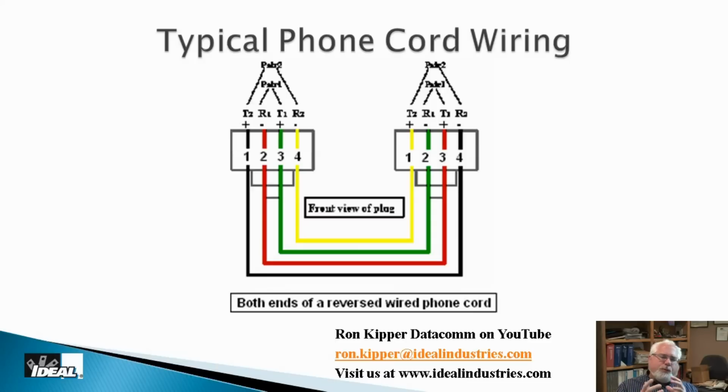And if you want to think of this as transmit to receive, you kind of can. And, in computer networks, a lot of us know that 10 and 100 base T, we're only using 2 of the pairs. One's a transmit, one's a receive, and we do that flipping, but we do that in the equipment, not in the cable. Where in old phone circuits, we actually did it in the cable.